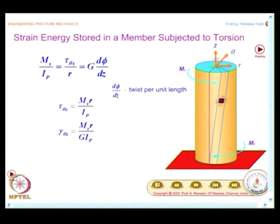Now, we take up what is the strain energy stored in a member subjected to torsion. We have already developed, when you have stresses and strains, simply a product 1/2 of that into volume gives you the strain energy stored. We will adopt a similar approach here. You have a torsion formula.